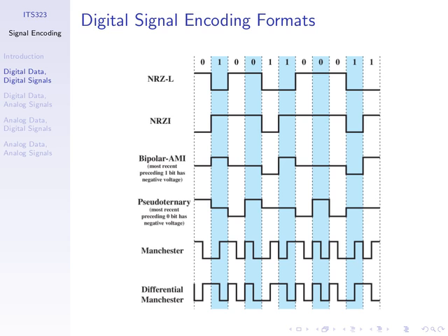If the receiver receives this, it detects an error. It doesn't expect to receive this, because we've got high, low, low. It should be high, low, high, low, high, low, and so on. So immediately, using this encoding scheme, the receiver can detect an error.